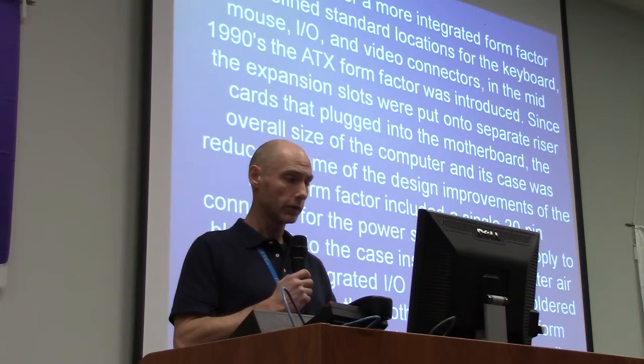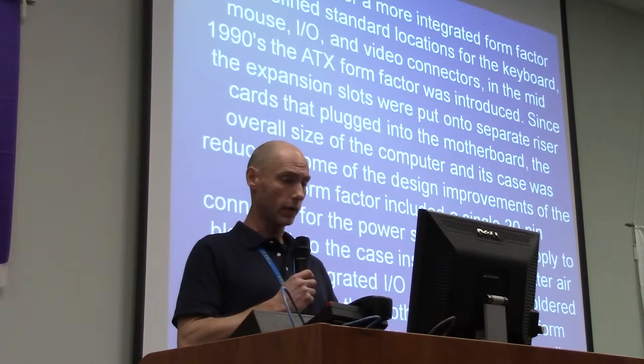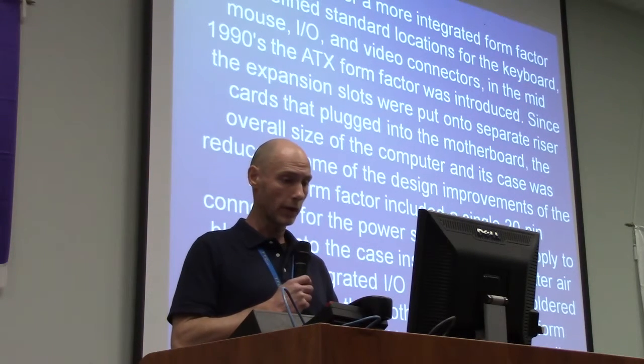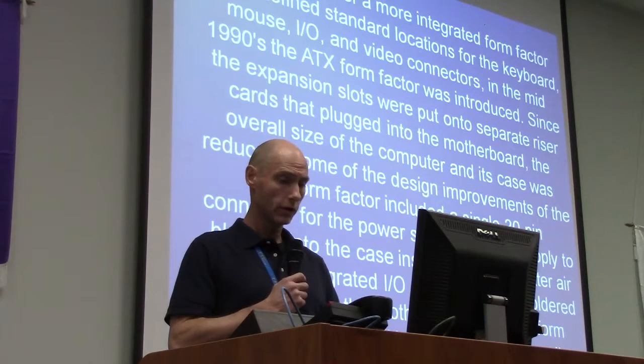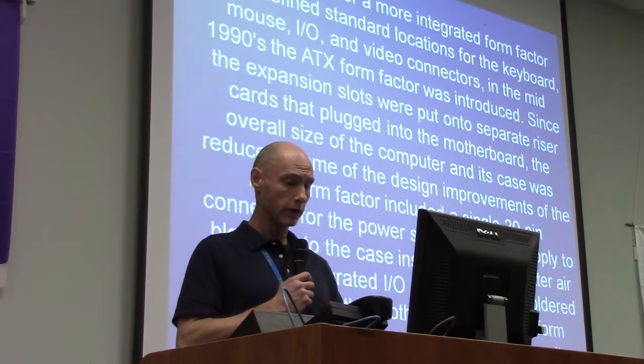Some of the design improvements of the ATX form factor included a single 20-pin connector for the power supply, a fan to blow air into the case instead of out for better airflow, and integrated I/O port connectors soldered directly onto the motherboard. The ATX form factor was an overall better design for upgrading.